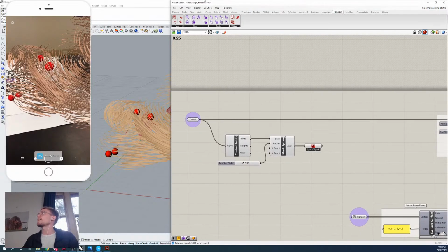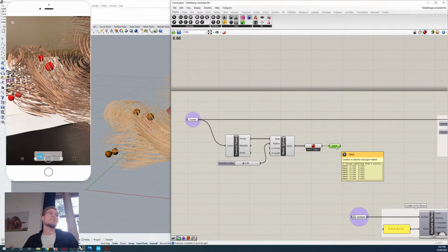Then I just want to create a mesh container, and there's a reason for that. There's a component we need to use that has a little bit of a bug with it. So I just want to create a mesh container just to clarify that that's coming out as a mesh. You'll see I've got 7 meshes coming out into that one, which are my 7 mesh spheres that I've created that are going to serve as our control point spheres.